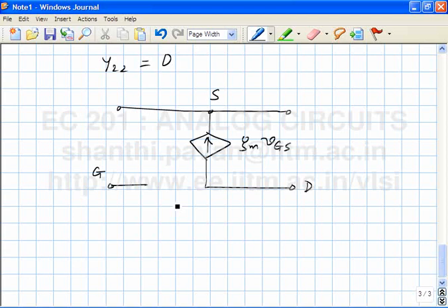There are many ways of realizing the same incremental equivalent. We have seen this, the common source amplifier, we have realized using so many ways of biasing: you push current into the drain, feedback here, feedback there, all sorts of stuff. So for a given incremental equivalent circuit, there are many ways of realizing it, even if you only restricted the implementation to contain only NMOS devices. Now, you see that for the same incremental equivalent circuit, you can also use PMOS devices. So the number of circuits that you have has doubled because everywhere you have an NMOS transistor, you can replace it with a PMOS transistor with the appropriate biasing. And now if you think of combining NMOS and PMOS, the number of circuits will just explode.